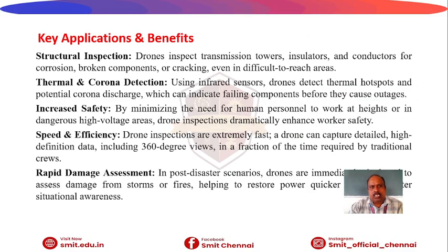So what are the key applications and benefits in the case of transmission and power distribution systems? Mainly structural inspections. The drone inspects transmission towers, insulators and conductors for corrosion, broken components or cracking, even in difficult to reach areas. Then thermal and corona detection.